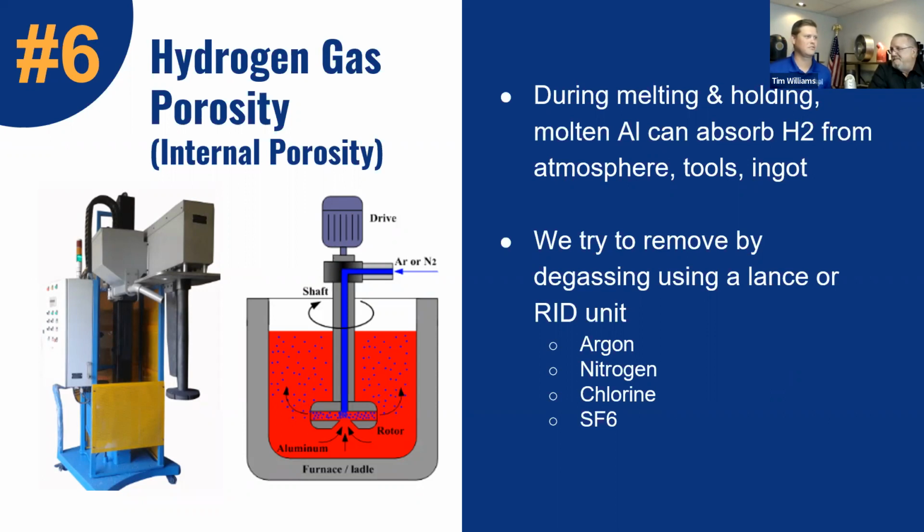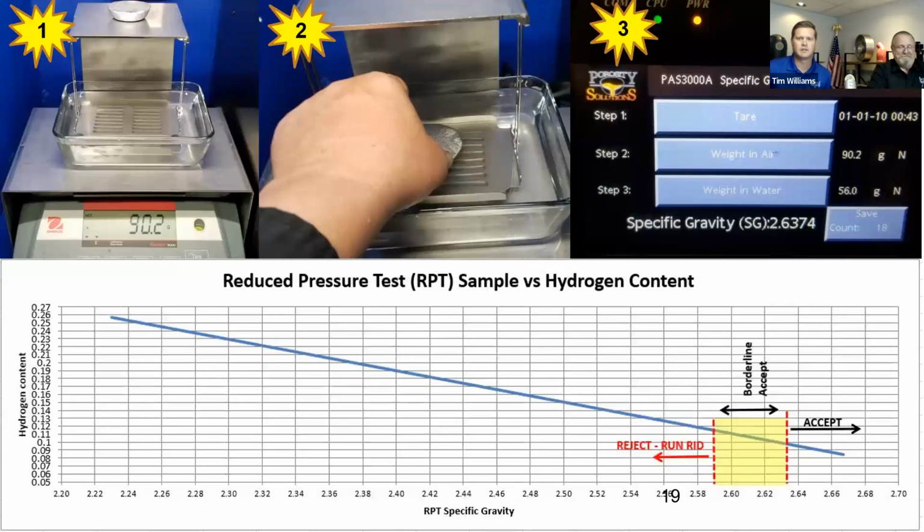I mean, if a customer is designing a mechanically sound product that needs to withstand certain tensile strength, you try to eliminate some of this hydrogen gas porosity. But I think you hit the nail on the head there, guys, with the medical and food industry, where it's very important that nothing's getting into it. So from the surface perspective, it's very important that there's a high-end finish on the surface, whereas internally it may not be as important. So, good discussion. Yeah, that second question was, how much does chemistry impact the hydrogen levels?